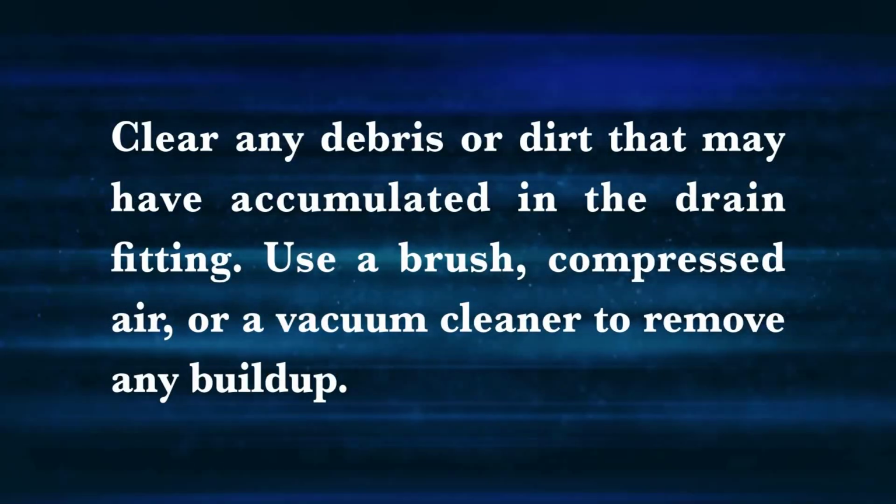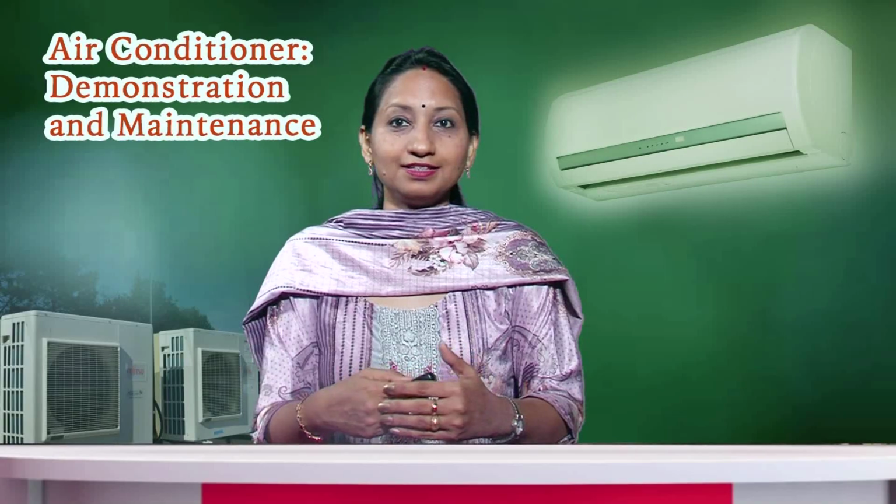Use a brush, compressed air or a vacuum cleaner to remove any buildup. Inspect the seals and connections around the condensate drain fitting for signs of wear and deterioration. Replace any damaged seals to prevent leaks, otherwise it can damage the control board and other furnace parts.